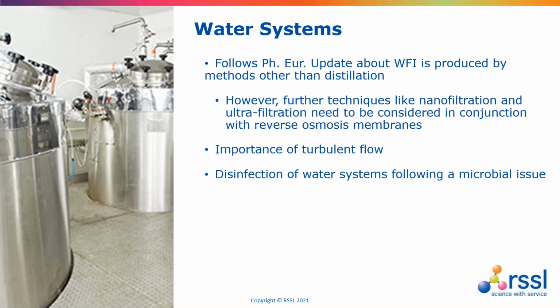However, there is emphasis and warnings around reverse osmosis, and that it is not as robust as distillation, because there is the weakness if biofilm buildup develops on the filter, and of endotoxins as well. So it's not saying that RO is no good, but the number of controls and care and inspection of RO systems is always going to be higher as well.